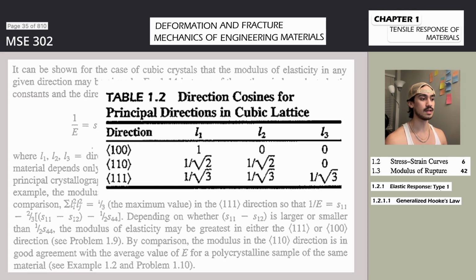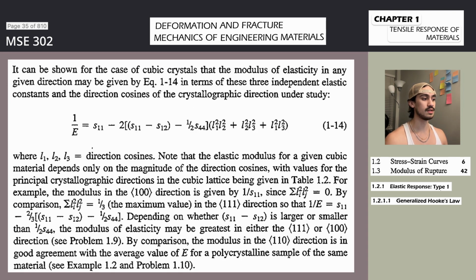A much more important material property is the yield strength, a stress level related to the onset of irreversible plastic deformation. This quantity is difficult to define, since the point where plastic flow is found will depend on the sensitivity of the displacement transducer. The more sensitive the gauge, the lower the stress level where plastic flow is found. In recent years, special capacitance strain gauges have been used to measure strains in the range of 10 to the -6. In fact, a number of studies dealing with the mechanical behavior of materials in the microstrain region have been undertaken as a result of this breakthrough in instrumentation.